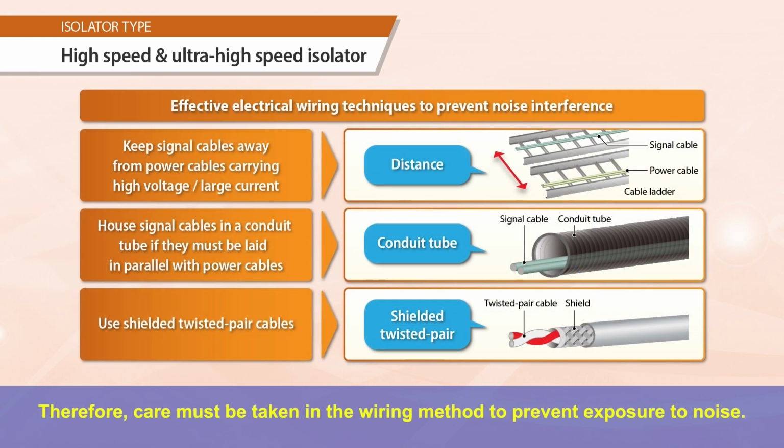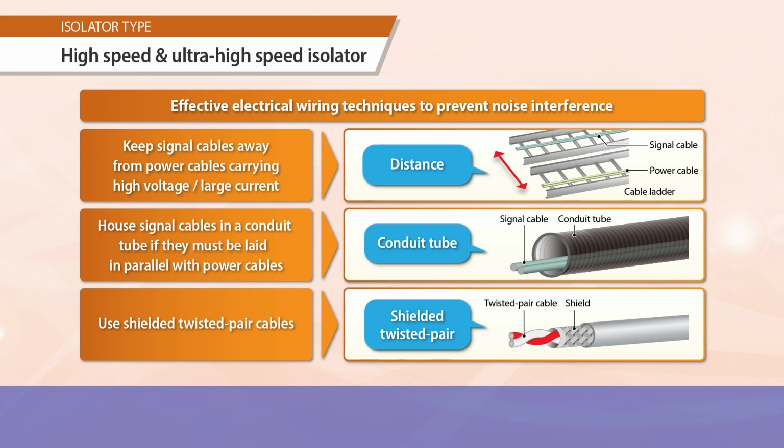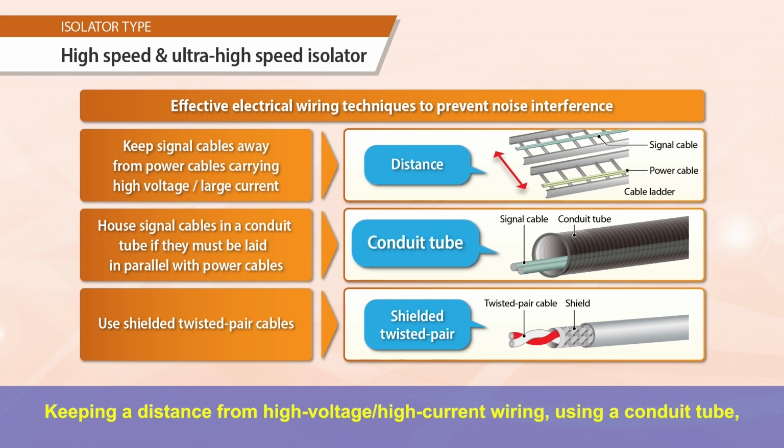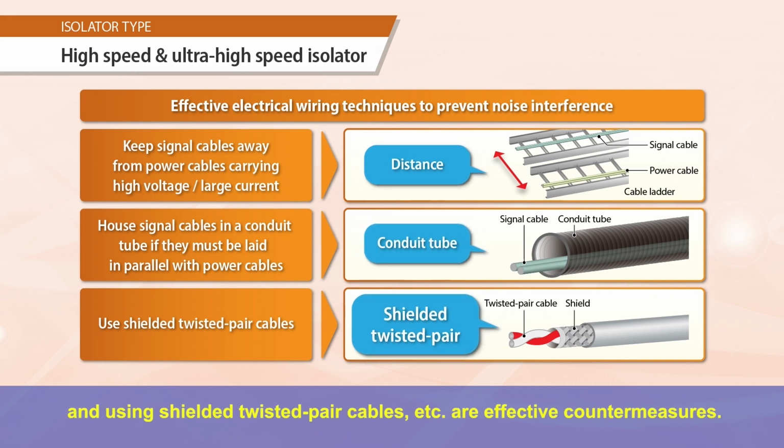Therefore, care must be taken in the wiring method to prevent exposure to noise. Keeping a distance from high voltage, high current wiring, using a conduit tube, and using shielded twisted pair cables, etc., are effective countermeasures.